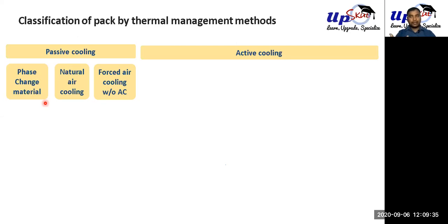That is the principle that is being used. So instead of adding a heat exchanger, we are adding a material. When the temperature of the battery increases, the material starts to melt. While the material is melting, it is absorbing all the heat as latent heat, and it's not letting the battery temperature go beyond that range. So this kind of material is good for small fluctuations, but slow also, because this is a slow process. That's why it's not very popular.